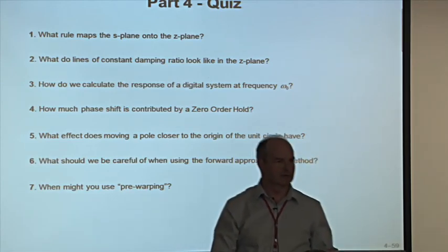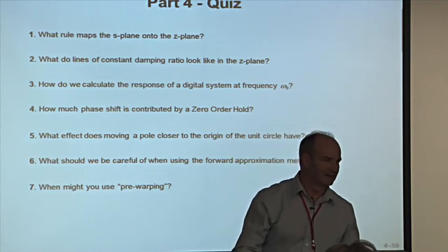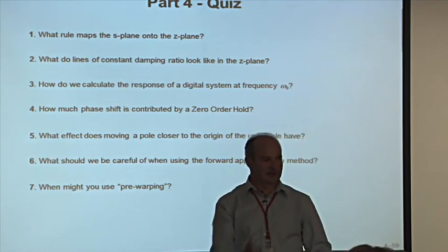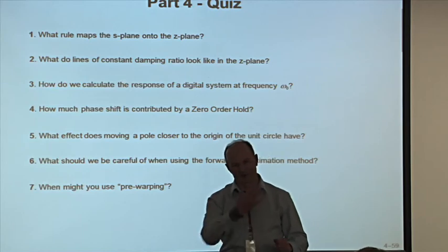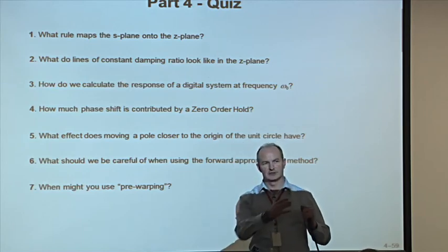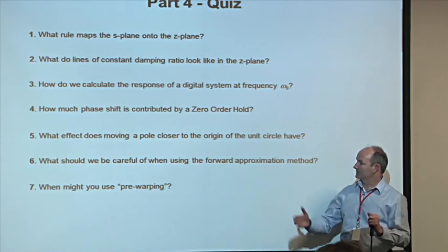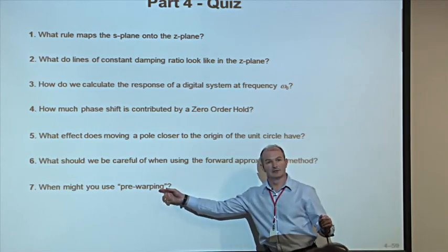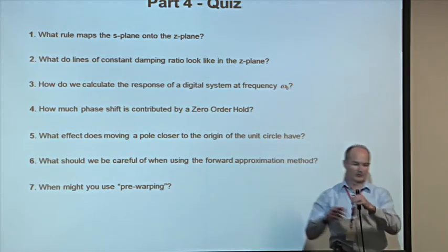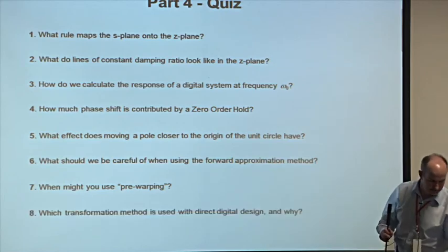People don't shout. Somebody? Tustin. I know somebody said Tustin there, so I'm going to give you that, Tustin. Lucky there's no T-shirt associated with that, otherwise you'd definitely get one. Tustin method. You use Tustin, but before you apply Tustin, you apply pre-warping to move the poles and zeros around so they're in the right locations.